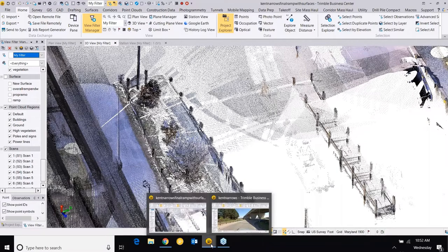Good question here. How to overcome moving objects during data collection, like vehicles or boats. The SX10 features the ability to do multiple passes. If you have a vehicle or something moving in your way in front of your station setup, the chances are maybe it'll shoot it for pass 1, but the recommended setting would be to do 4 passes, so you still have 3 other passes to pick up the data.